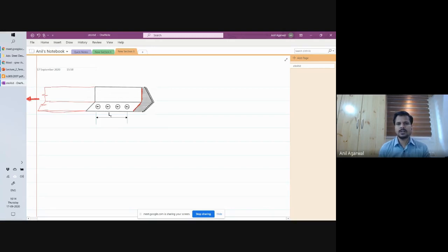But right near where the joint is, this is where it is tied. This angle is tied to, let's say, some kind of a gusset plate. That gusset plate is behind the angle, so I'm drawing it in a broken line. The plane of the gusset plate is parallel to the plane of the angle. And to this gusset plate, the angle has been connected through these 4 bolts.